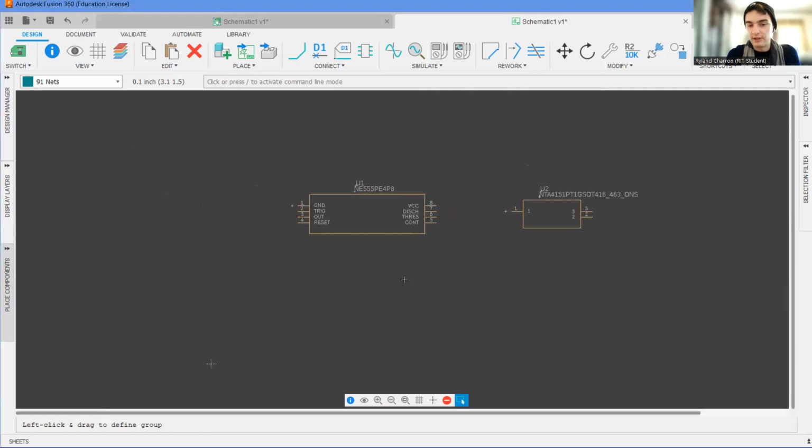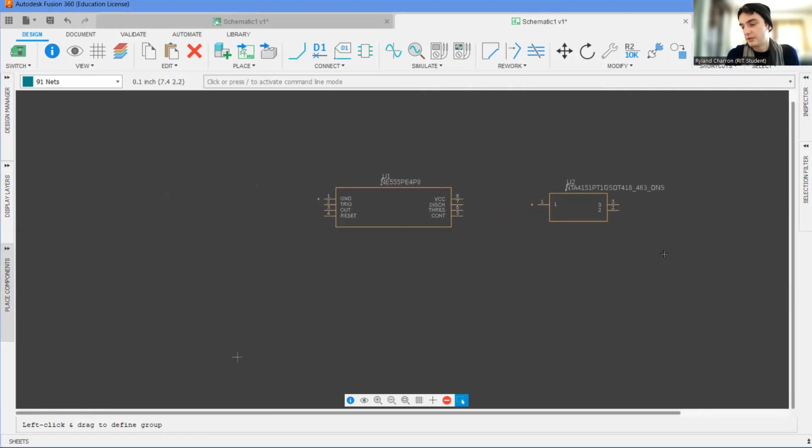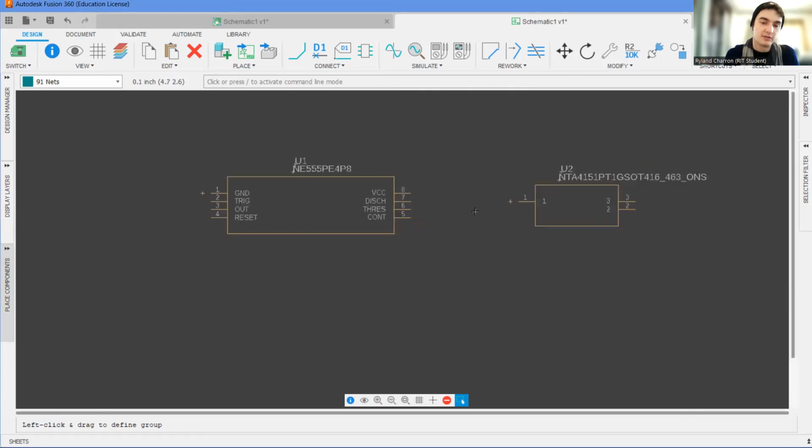All right, what else are we going to need? We got the timer. We got the transistor. We need 2 resistors, 2 capacitors, well, 2 1 microfarad, 0.1 microfarad capacitors, and 1 .01 microfarad capacitor, and then 4 just standard header pins to interface with the Arduino. And all of that is in the schematic we were looking at. I would have to reshare to show you again, but it's there. So I'm just going to start adding those things.